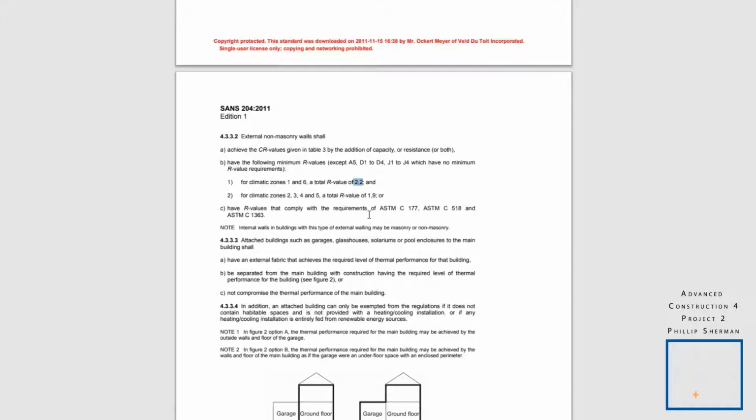Different materials have a certain R value level. It is important for you to find out that the gypsum board that Marley supplies, what is its resistance value? It might be 0.31, it might be 2, it might be 1.5. I am not sure, that's the task for you to do, but the wall calculation, you need to get to 2.2.